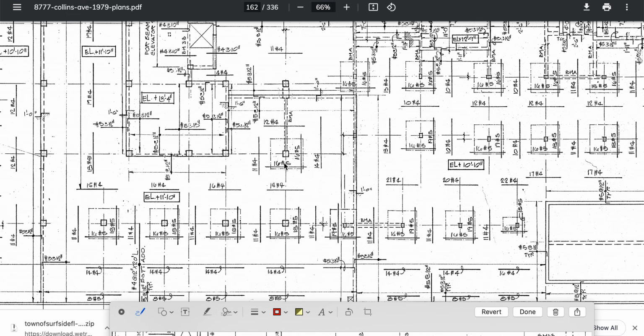This is where I'm going to get into tributary areas. It comes across and it meets this, wait a minute. It meets the column. Well, wait a minute, it doesn't meet any column. It doesn't meet the column here. It doesn't meet it here. It doesn't meet it all the way out here, where it breaks at the pool area. So you've got this steel coming across that meets no columns. It meets no tributary, no other areas is another name for it.